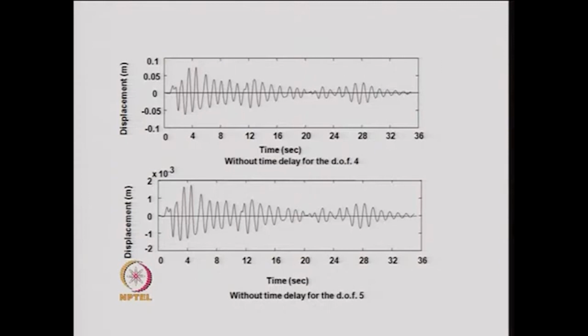Now, this problem was solved for two cases. In one case, we considered a time delay, and in another case, we assumed that there is no time delay between the two supports. So, this is the result shown for the without time delay case, that is, in both the supports we had the same ground motion of 30 seconds, and we continued the integration till 35 seconds. After 30 seconds, the responses that we see are due to the free vibration of the problem.